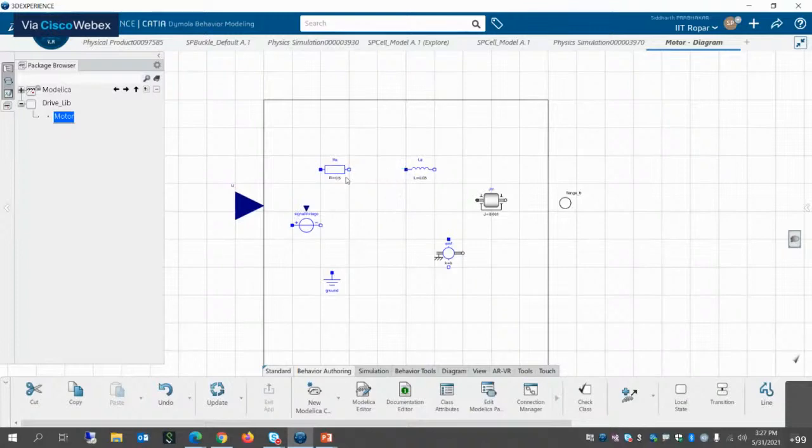Now the simpler method is basically click on your component, drag the component to the other component and just attach it. So you saw that green bubble that appeared. The green bubble basically shows the contact has been established and you can bring it back to its original place. This is a much simpler way of creating a contact. I'll show you the process again. Just click on the component, drag it to the other component, wait till the green bubble appears and drag it back to its original place. So that's how simple it is to create a connection.